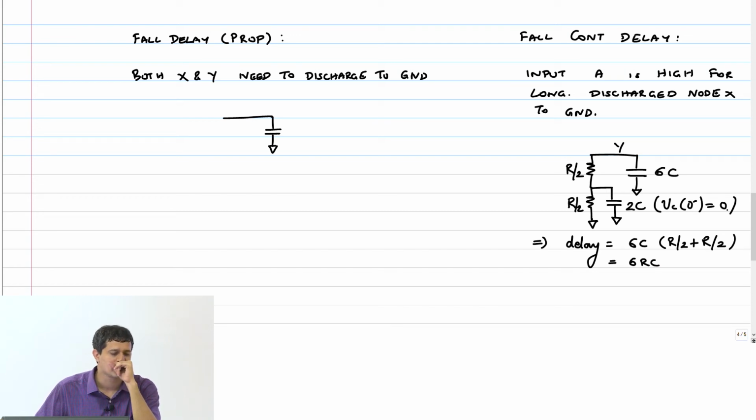True. So that's where the approximation that we made for this Elmore delay model comes in. It is true that this node, for it to accommodate some current, will actually bump up slightly. So this is only an approximate answer. It's not an exact answer. That node has to bump up slightly to allow some current, and therefore you will have some charging of this capacitor also slightly in the process.